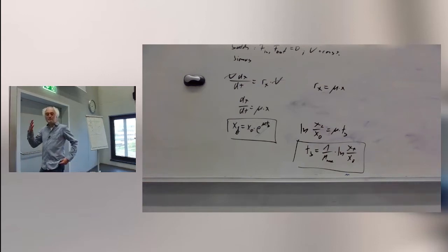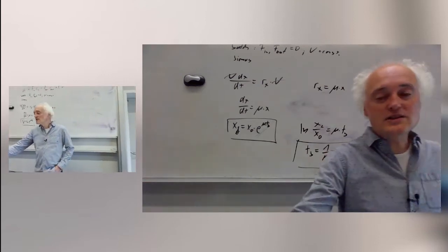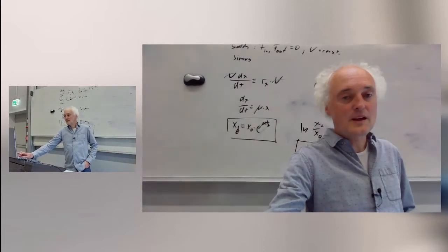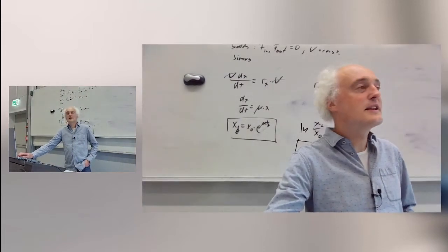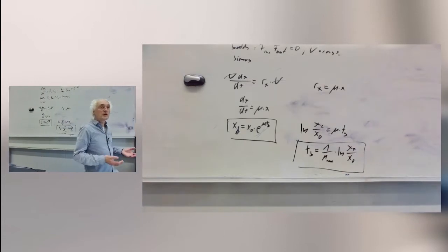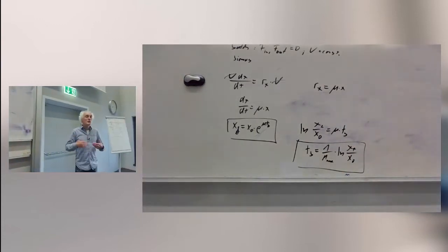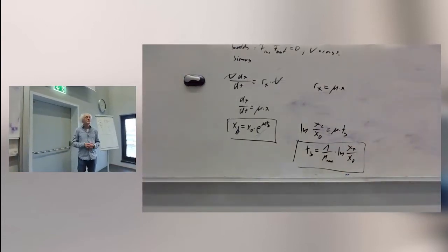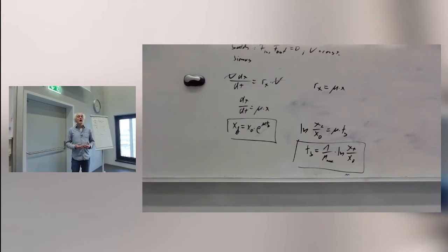So this is batch. And of course, you can also calculate the batch time for how much product is being produced and so on, which we will do in the real lecture. But at the end, you want to know how long it takes to produce X gram product, or Y gram biomass, or if I have consumed my substrate and so on. And then you just use the rates and so on. You can solve the equation and then you calculate it.